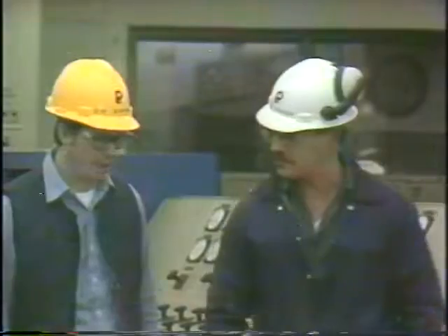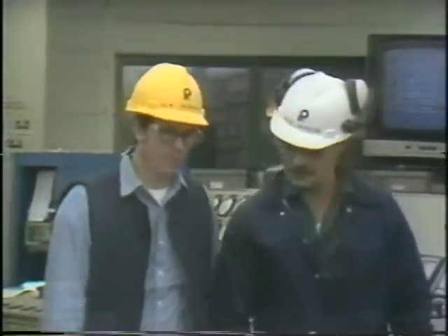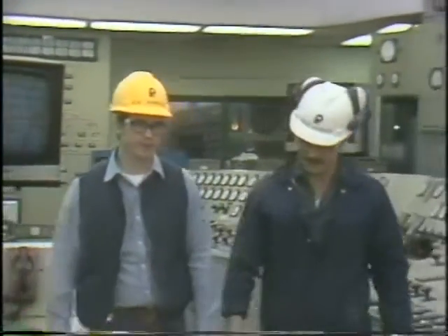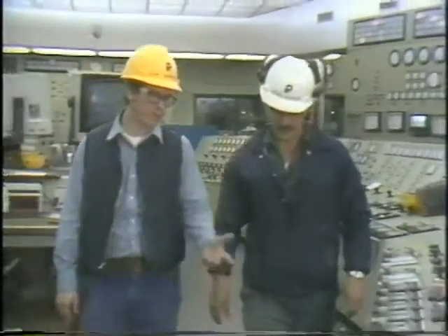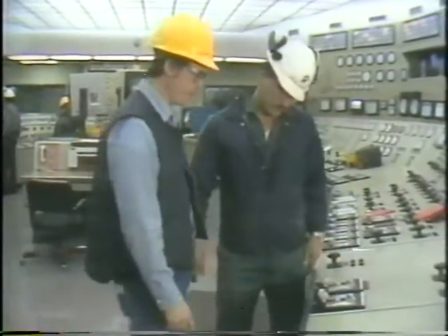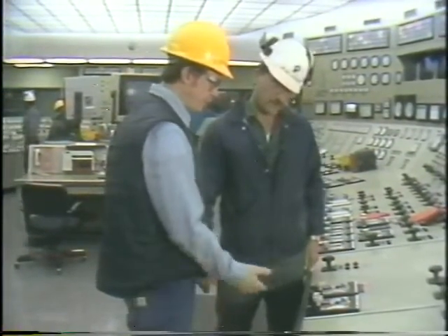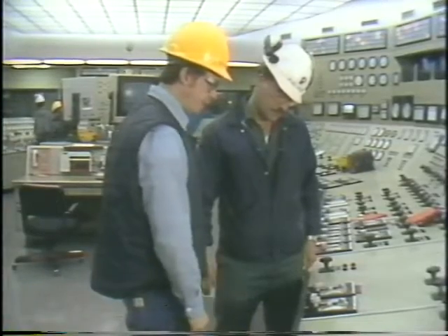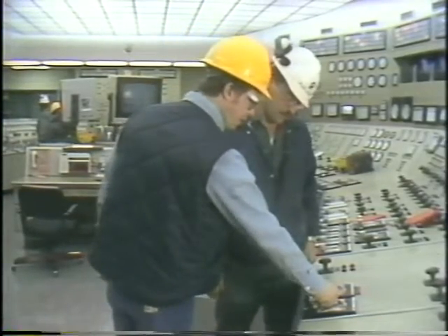While you were studying the various plant documents in the shop, you were able to learn about what the system's designed to do and how it's supposed to operate normally. Well, now see if you can find out from the operator what the abnormal operating conditions are. Ask him, for example, whether he noticed anything unusual or peculiar about the operation of the system. Find out from him if the problem started while the process was steady or whether it was being increased or decreased.